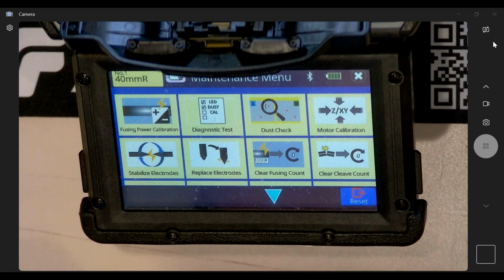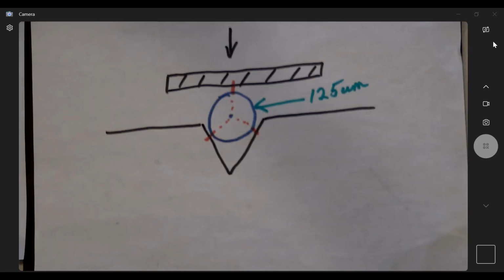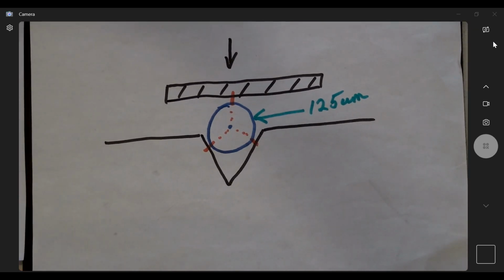So I'm going to take another view, which would be an overhead view of a little drawing that I produced, and show that to you. Very simple drawing that I want to bring to light. The main function of any fusion splicer is to align that core for maximum core alignment. With an active profile alignment system, such as a 90S active fusion machine, the V groove would move. But whether it be a fixed V groove, an active profile alignment system, or a cladding alignment system, all the Fujikura product line would hold the fiber the same way.